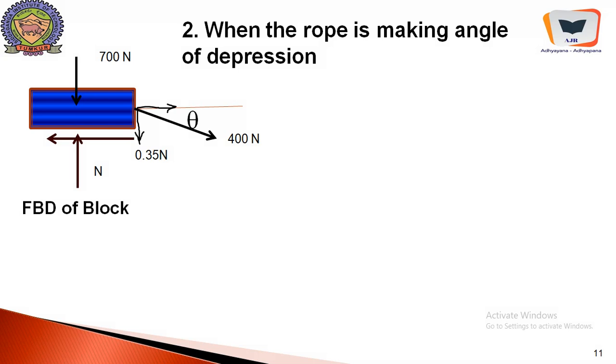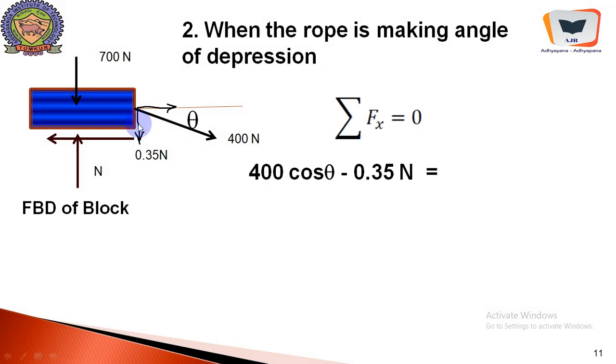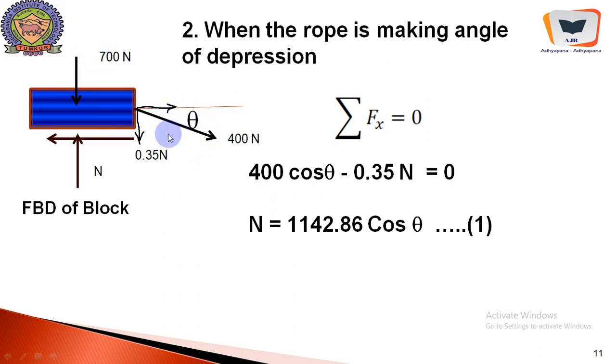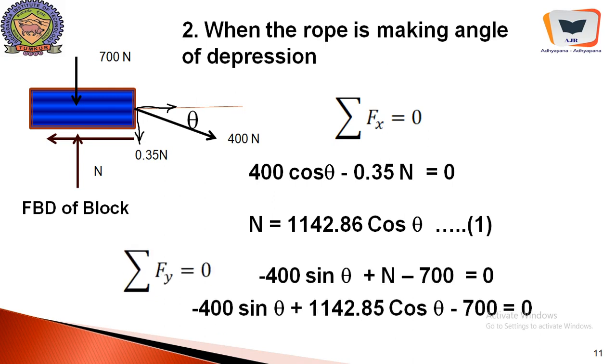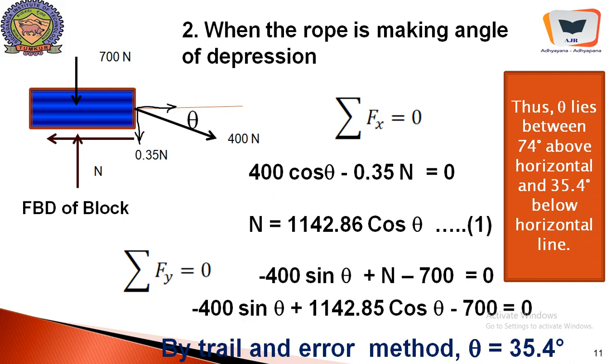As far as angle of depression is concerned, there is a limit, because it goes on adding to the weight, and if the weight is increased due to this particular vertical component of 400 Newton, it generates tremendous amount of friction. Therefore we need much greater effort in order to pull this block rightwards. That is the learning that happened in this particular problem.